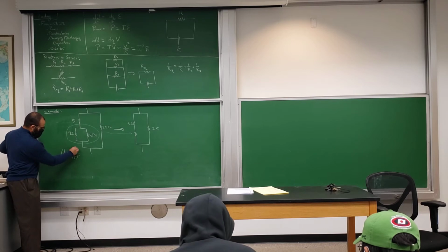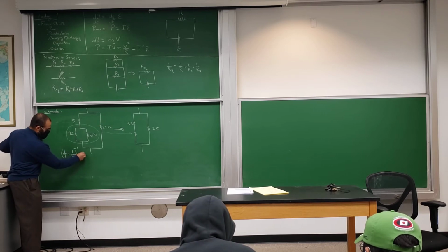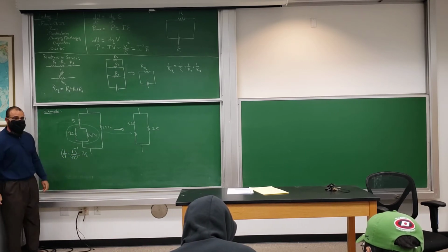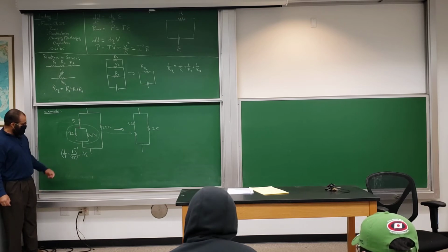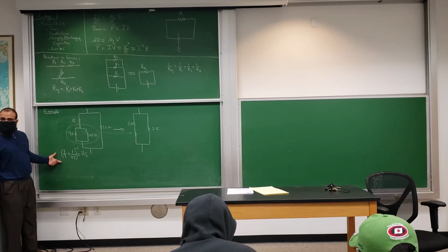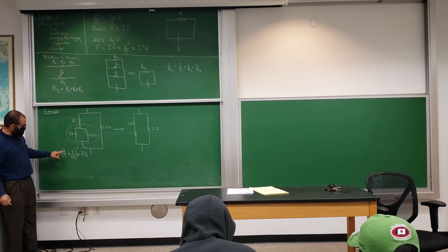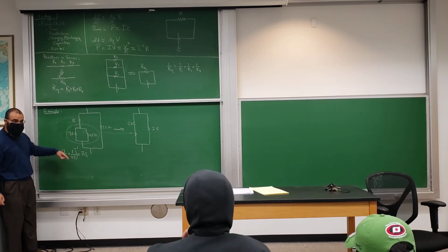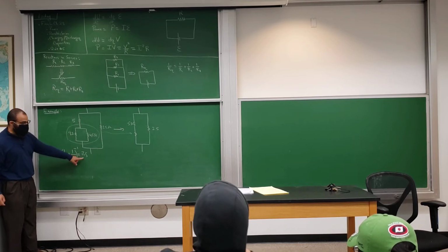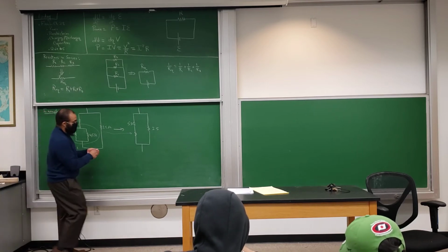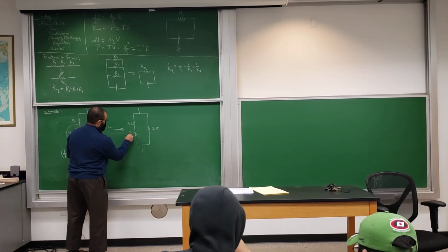When you reciprocate, you put it to the power minus 1, so 7.5 ohms. Is everybody clear on this? If you're not, you should plug it into your calculator and do it for real. Put 1 over 9 plus 1 over 45, and then do 1 over that result, and you should get 7.5 ohms. So this becomes 7.5 ohms.